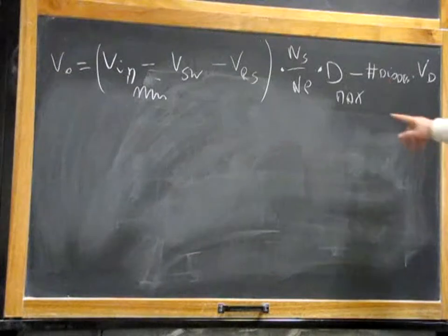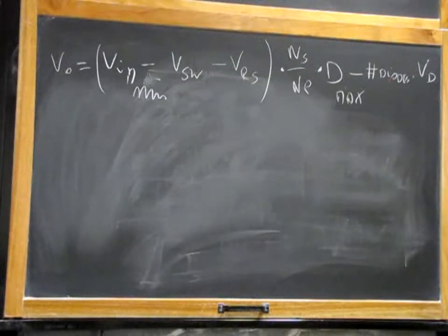If your duty cycle is 0.95, yeah, probably you could have it working, but you have no dynamic headroom. That means if you need to increase suddenly the output current, and to increase the output current through the inductor, you need volts and seconds, you need voltage and time. You don't have enough voltage to be applied.